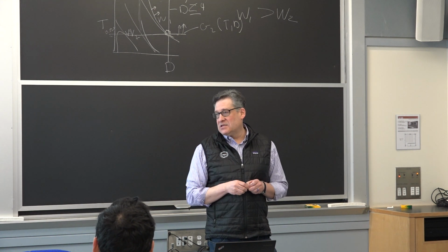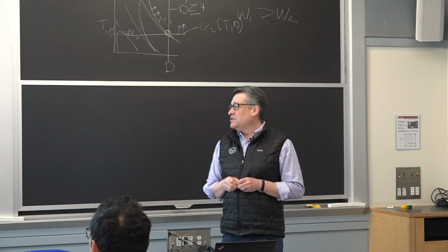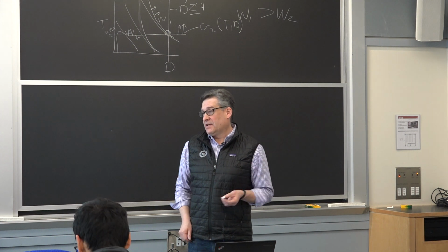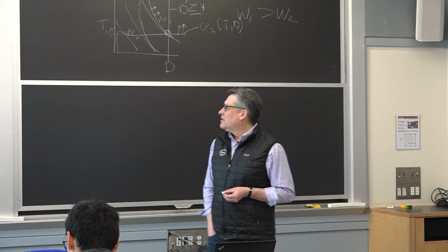And this is, by the way, this is another, what's your name again? Tim, this is another place where you could use your factor of safety right here in this constraint. Maybe this material is a 30 KSI material, but you're only going to say 20 is what we're going to let it see.